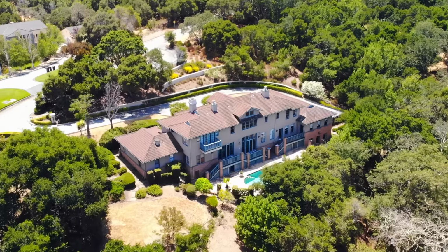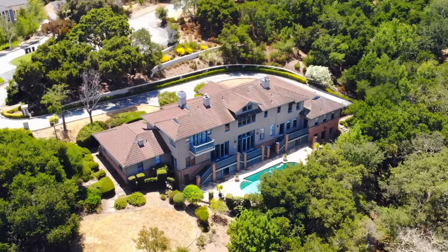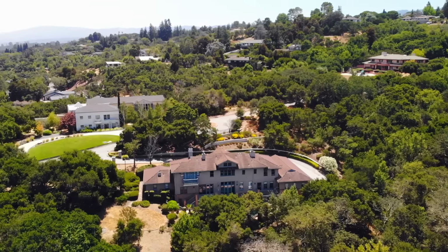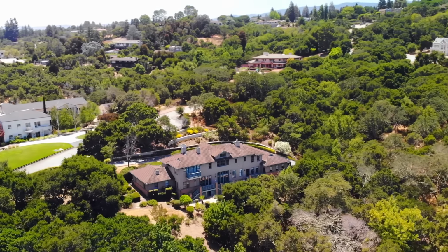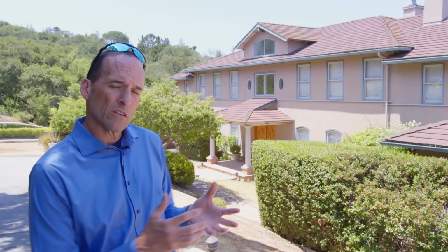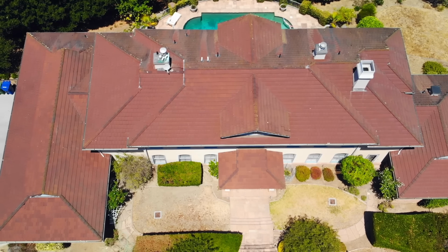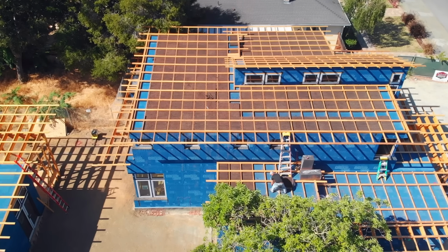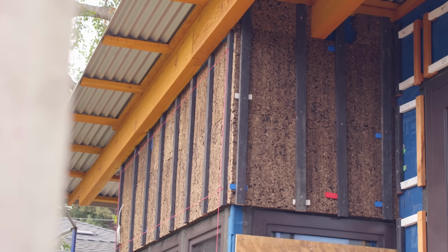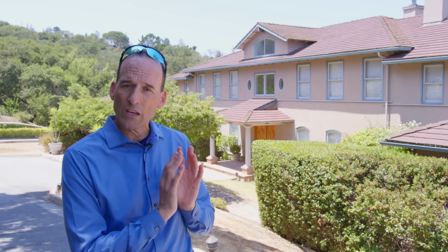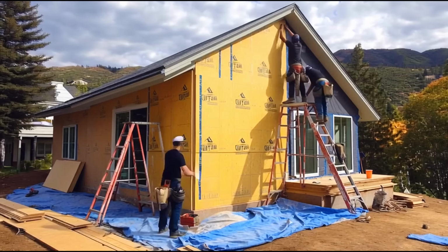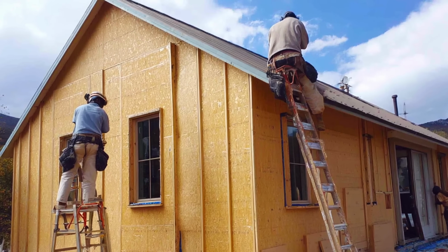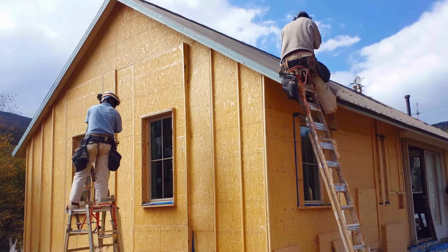This project is about a 6,000 square foot house in the hills above the Silicon Valley. We're going to talk about how we make this house more cost effective. Now, what does that mean? Well, when we originally came up with the design with the architects on this project, we talked about removing the roof and about putting exterior insulation on the roof and on the walls. Typically in passive house projects, you put insulation on the outside of your envelope to reduce the amount of conduction you get through the studs and to make sure that that whole building is more energy efficient.